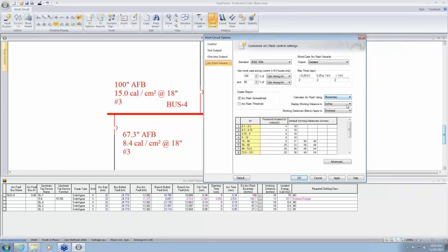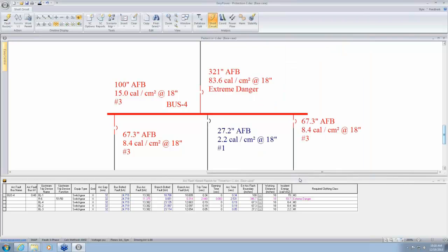So when I do that, my arc flash results are going to change for those buses for which the calculated trip time was higher than 2 seconds. Now you see some values changed out here, and it got limited to 2 seconds there.